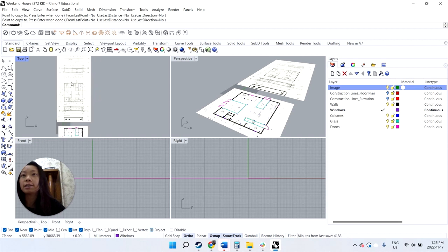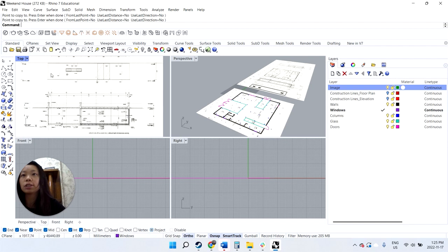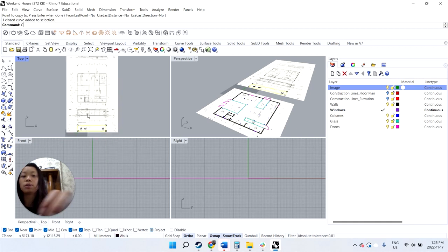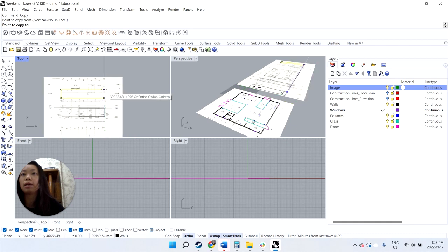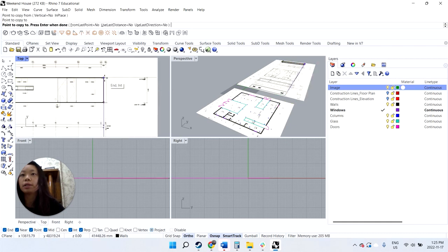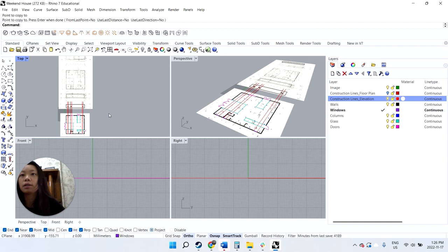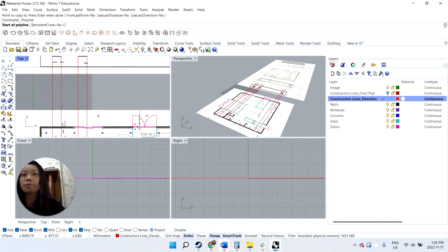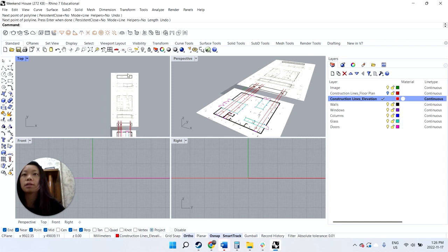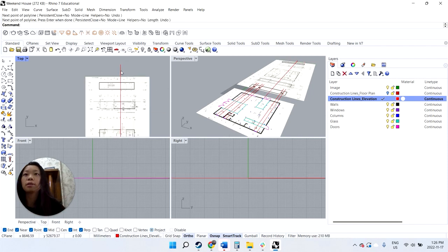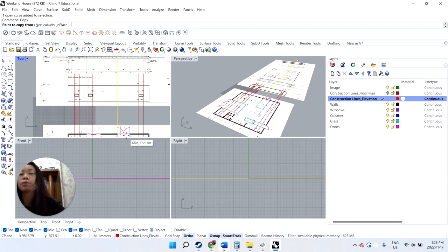You can imagine this is kind of like a net unfolded, so you'll notice that these elevations and sections are actually upside down. But yeah, we can still draw it as is and then go from there. Simple ways, because we know everything's the same height, I can simply copy maybe the outline of the building here. For some reason shifted. But again, we can turn on the construction lines, make that the active layer, and then we can simply maybe draw this all the way up to help create some of our elevation lines.